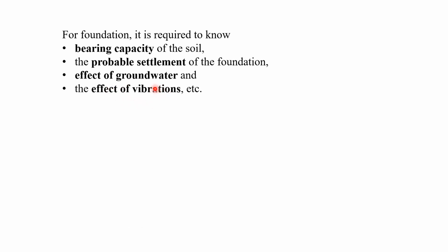The effect of vibrations. Suppose you are going to construct the structure nearby the mines. As you know, during the mining, vibration also occurs. So that point also we have to consider. What I'm trying to say is that without knowing these things, if you are going to construct the foundation, the geotechnical field problems will arise.